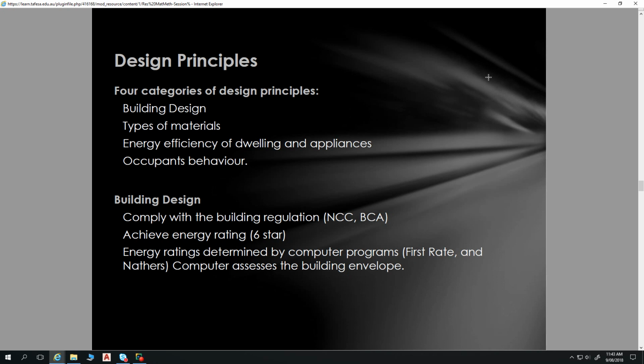Although the National Construction Code, and the BCA before it, has had a map of Australia divided up into climate zones for a very long time, there are many other considerations with that. But yes, down here on the plain in Adelaide, we're climate zone 5. In the hills, Victoria Peninsula, etc., it's climate zone 6. Areas of Tasmania, climate zone 7. Go up north, we've got climate zones 2 and 3. We have all these different zones because temperatures and winds and, well, climate do different things in these areas.